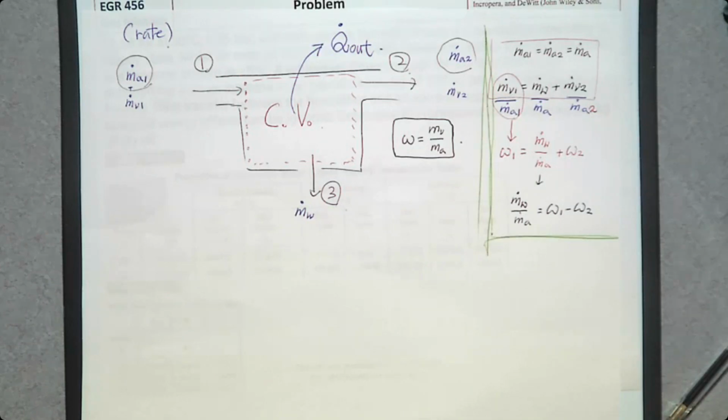There's no heat transfer in. There's only heat transfer out, because in a dehumidifier, we remove heat from this chamber so we can drop the temperature down to the dew point temperature. So there's no heat transfer that goes in. There's no energy transfer by work that goes in. There's only one energy transfer that goes in, that is the energy carried by this mass.